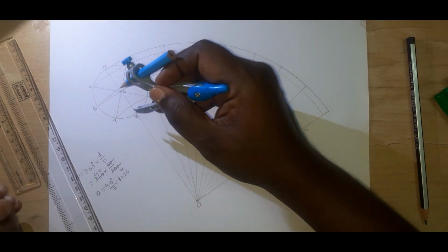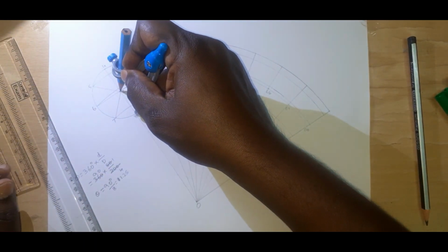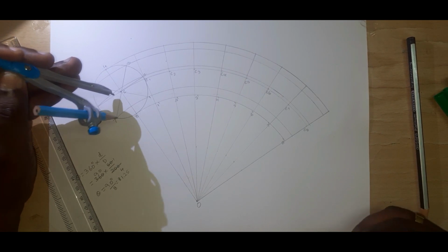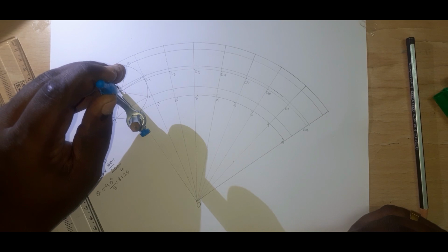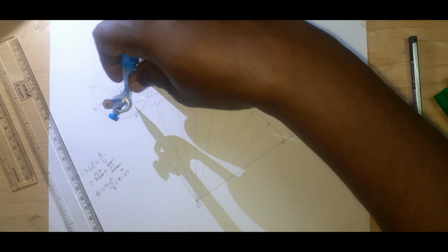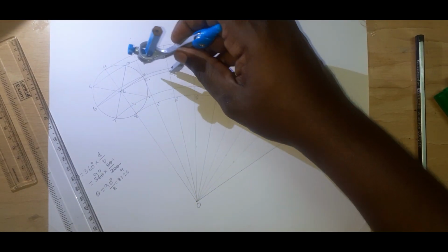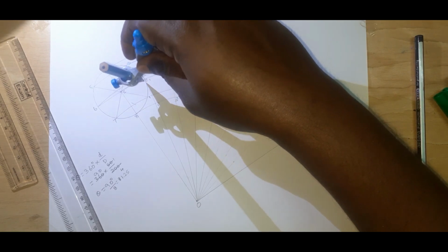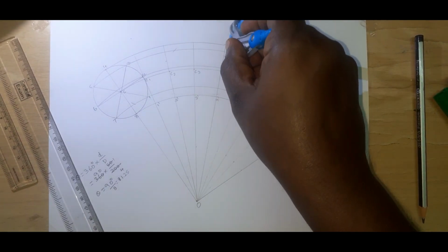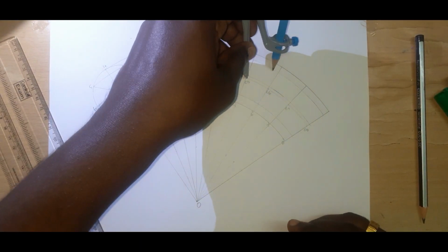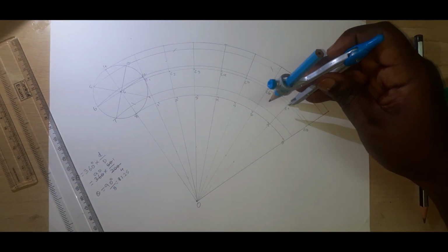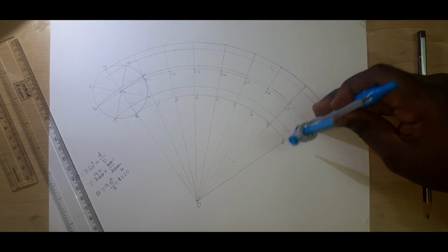Now, the main part. Here we measure the radius, that is 25 mm, already we know it, and the same way we did the previous one, here also we have to make it. The first arc is here, we made it, and the second arc here, just listen where I am going to fix it. C1 is on the first line locus. For C2, the locus is different, the second line locus, that is the above line, not the center line locus. Then C3 is here and C4 is here, then C5 here, then C6 is here, above line, not the center line. C7 will be here and C8 is here.